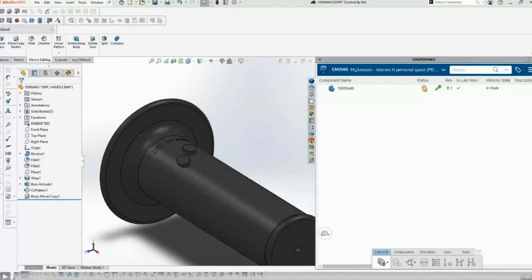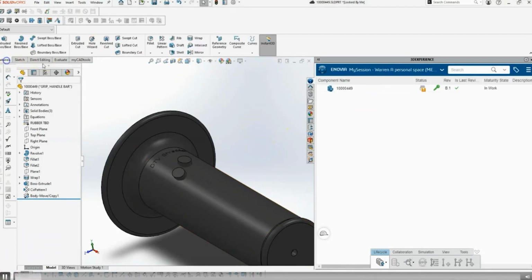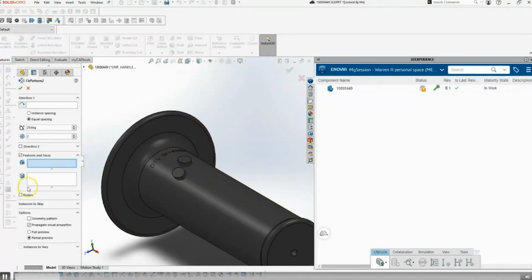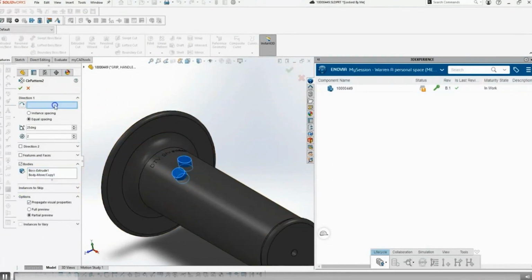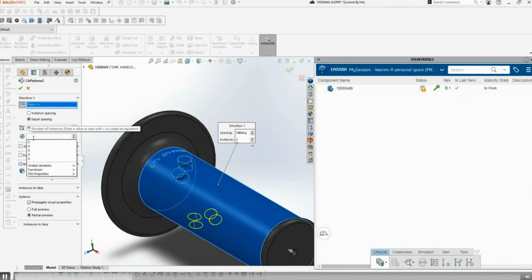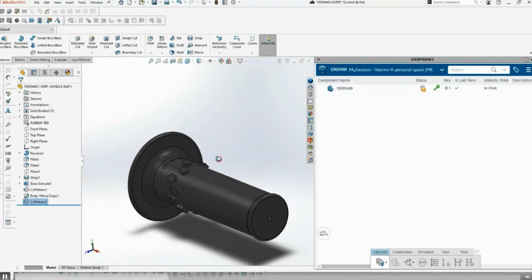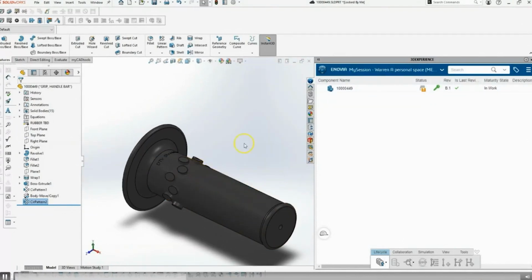So now I am ready to make more of an adjusting change. I'm actually now going to circular pattern this, and then once again, I'm going to do different types of patterning. So we're ready to create that circular pattern around this cylindrical face. I'm going to add the circular pattern, important for the 2 bodies, right? Cylindrical face or edge, and it's going to be 360 around, and it's going to fit about 7 in there. That should be good. So now that you have the circular pattern of those 2 bodies, it's coming out very nicely.